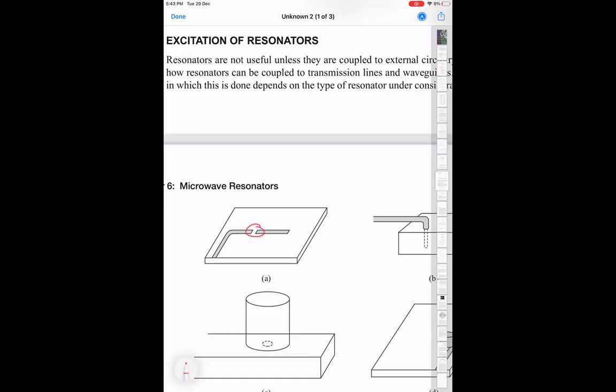And this they did by putting holes from opposite sides, which are slightly offset, so that every hole is different, but between them where they meet, inside a larger hole opens up, and then you have a continuous cavity. The reason for doing that was they are trying to minimize the losses of the cavity, and one loss comes from the fact that these are two pieces, and when you join them, there are actually currents which flow from one side to the other side, and that interface can have some kind of lamination and give some kind of resistance to the path of the current. So they wanted to make a cavity which has no joints. So this was a very clever way of doing this.